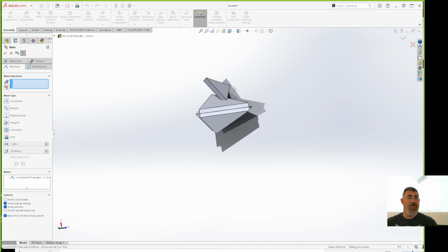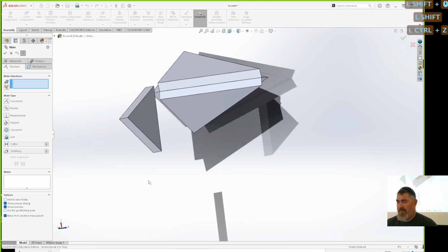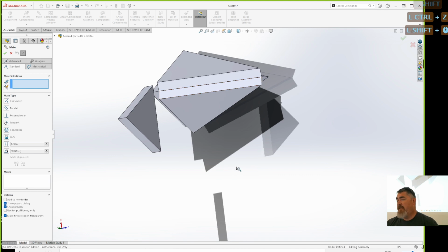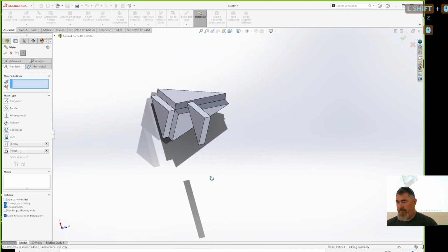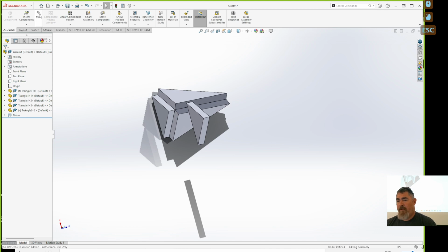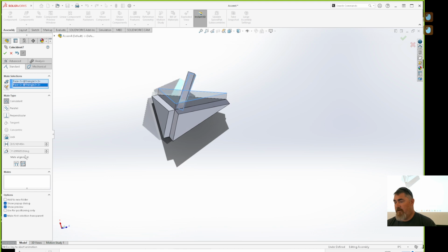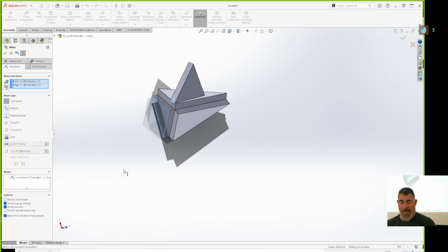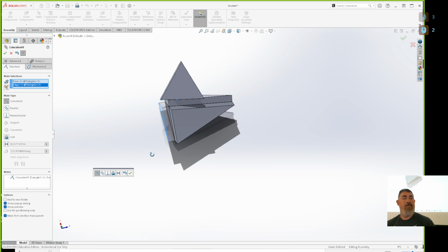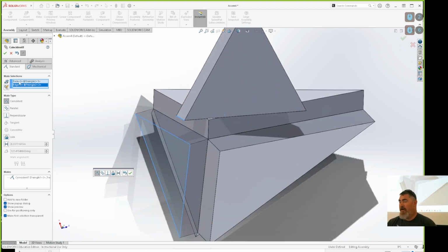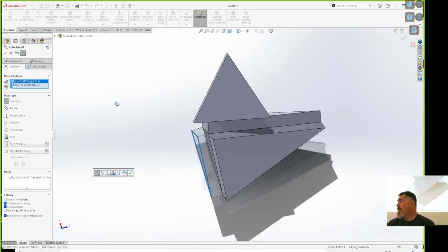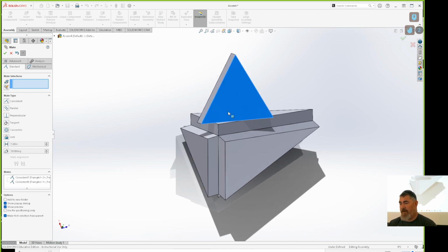And so it's not used as often, but one common use, besides just edge-to-edge stuff like this, is if I want this to be aligned with that and flipped. But now I want this edge to line up with where that face is. Yeah, I can do a mate between the face and the edge. Now the face will stay on that edge. So now it can only slide back and forth.